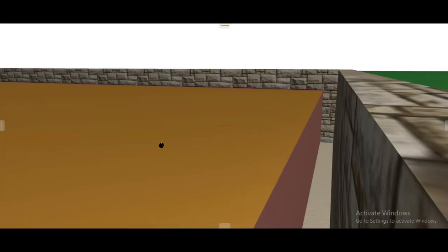So to demonstrate that backfilling, remember there's a void, this void now. After a foundation slab, we have this foundation wall, and because there's a trench which was dug here, this is the reduced level. So this void needs to be filled just before doing the hard coring over this, and it is having a depth of 0.85 meters from this edge down to this foundation slab.